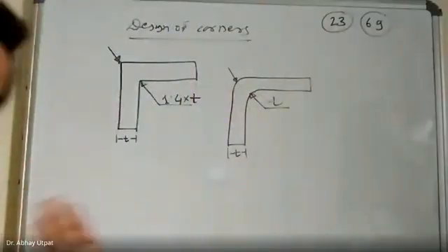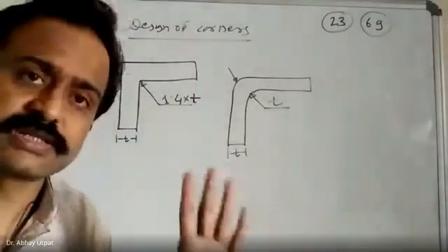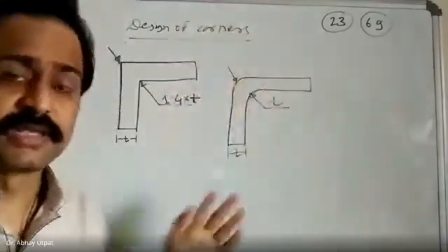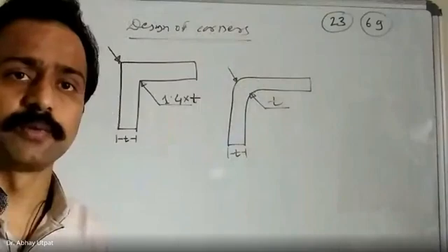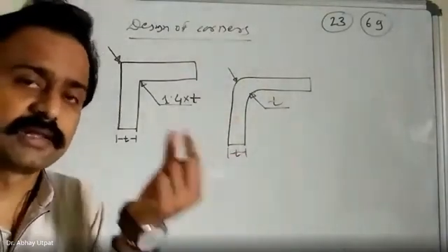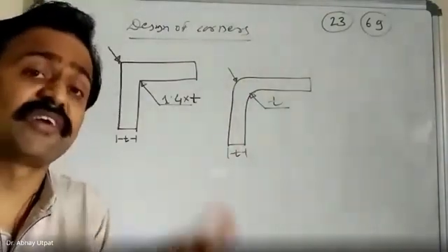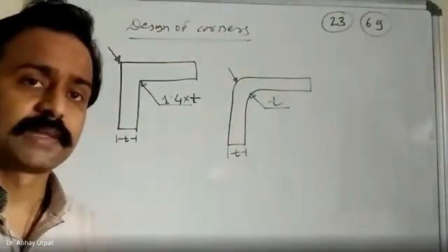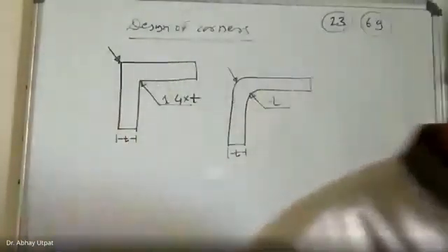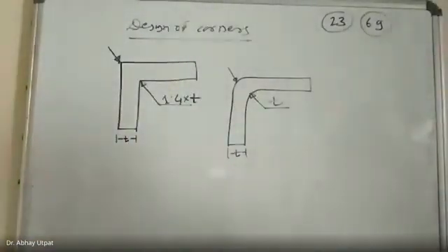We are not talking in terms of stress concentration, maybe generation of cracks. That aspect is totally different. Here, we are talking about the manufacturing aspect. When you are going to solidify your component, the thickness will affect the cooling rate. So that's why, while designing the parts, sharp corners are avoided. You can write this statement.